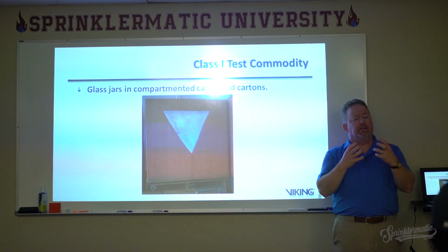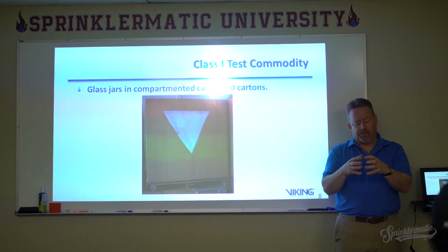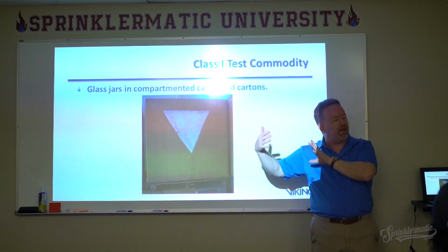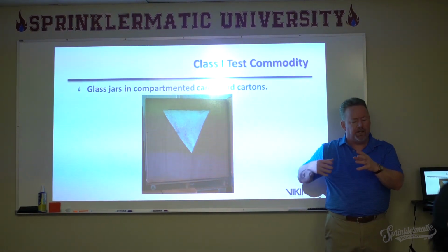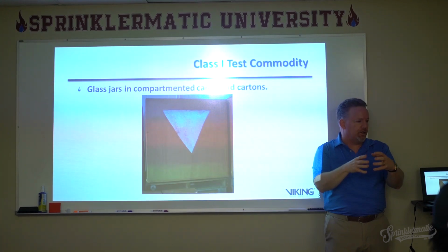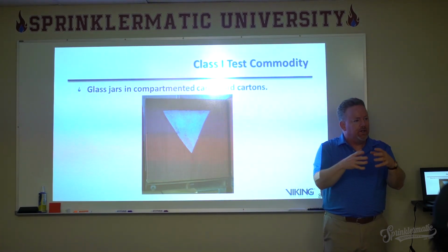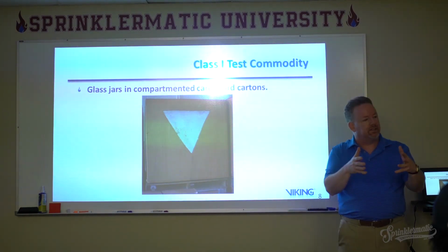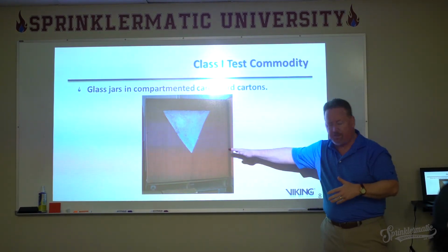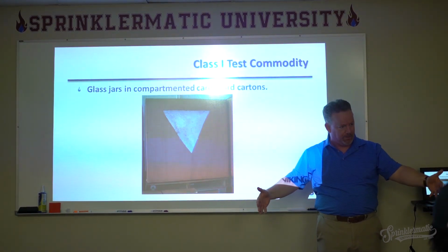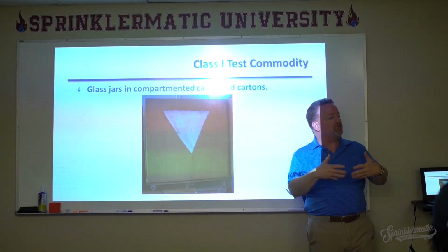What we have in the sprinkler industry typically is we convert this heat release rate. We look at how fast it burns, how much heat's coming off, and then we determine, through other tests, what we call its required delivered density. In other words, this commodity is going to burn at such a rate, it's going to require this much water to spray around it in order to control the fire.